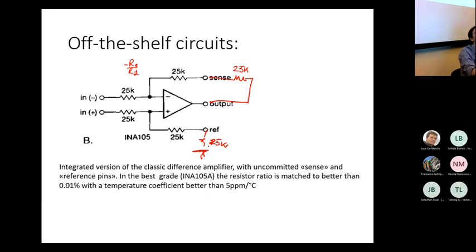But if we do so, the guarantee about the matching of the top and bottom branches is lost. Okay, so we have to indeed test the resistor values so that they are very accurate. We must control the contacting in this circuit to achieve a very precise matching between the resistors.